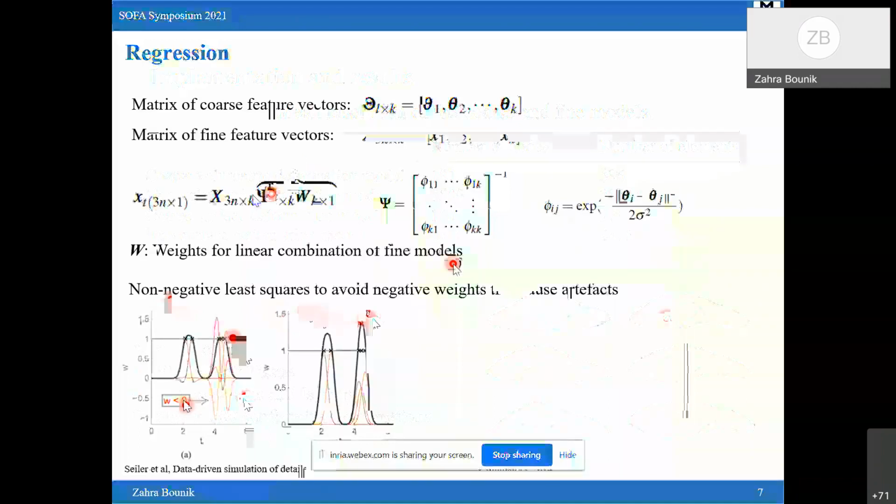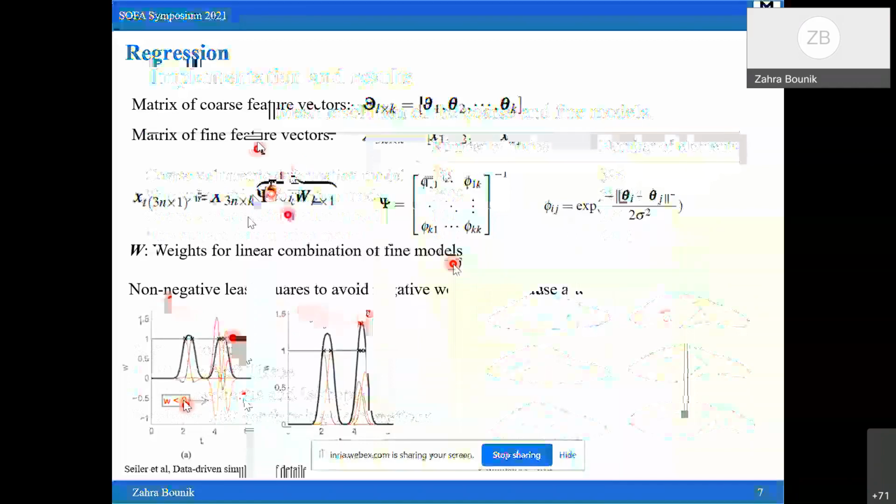For the implementation, we consider the mesh resolution as this, and we consider different coarse and fine volumetric and surface models. We also consider the fine and coarse visual deformations, the same as the fine surface deformation models. Our assumption is that the soft tissue is elastic, homogeneous, and isotropic.